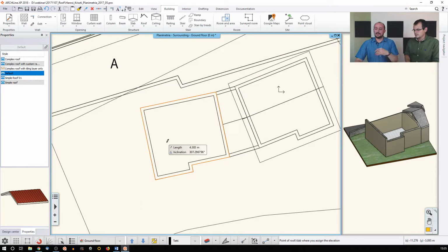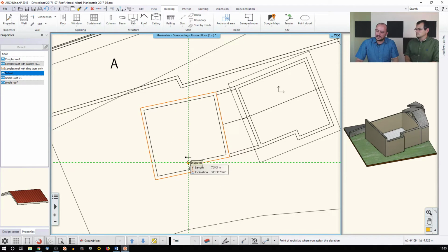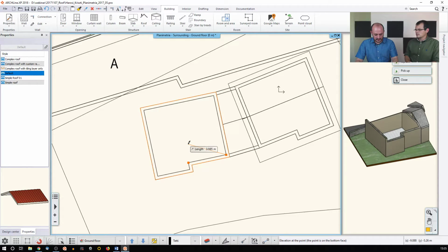click here, and then the second step is that I need to determine the first height that I know. Say I was measuring this here and it was 1 meter. Then I have to add the second point, this here, it was again 1 meter. And there was the entrance here and it was 2.4 meters, so I just click here and it was 2.4.